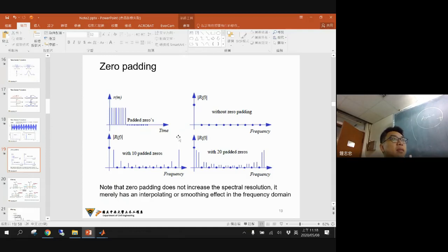Can I get a much better result from this kind of zero padding? Okay, I would like to say, yes, in the theory, you may increase the resolution in the frequency domain, however, the actual content in the frequency is the same.